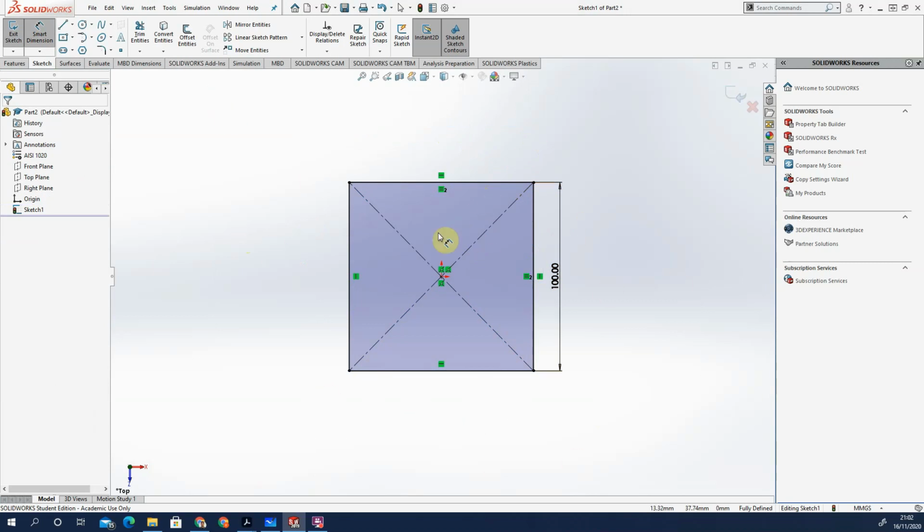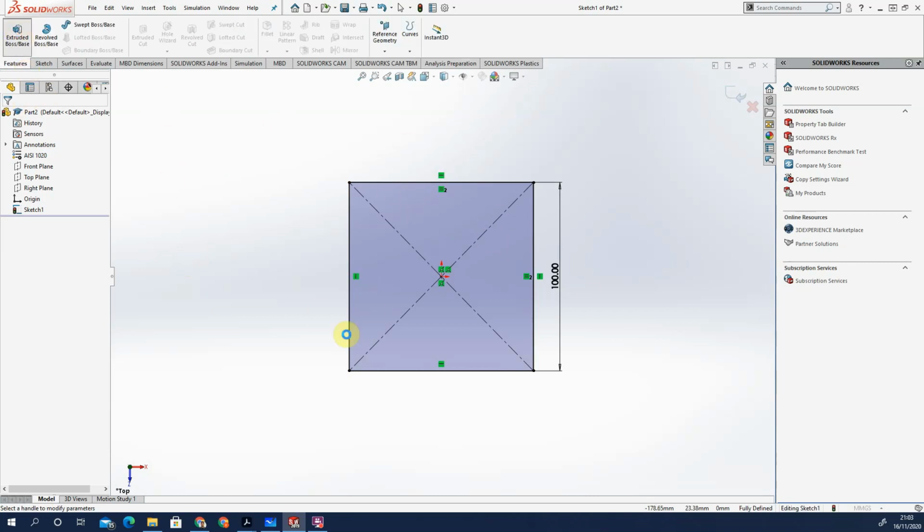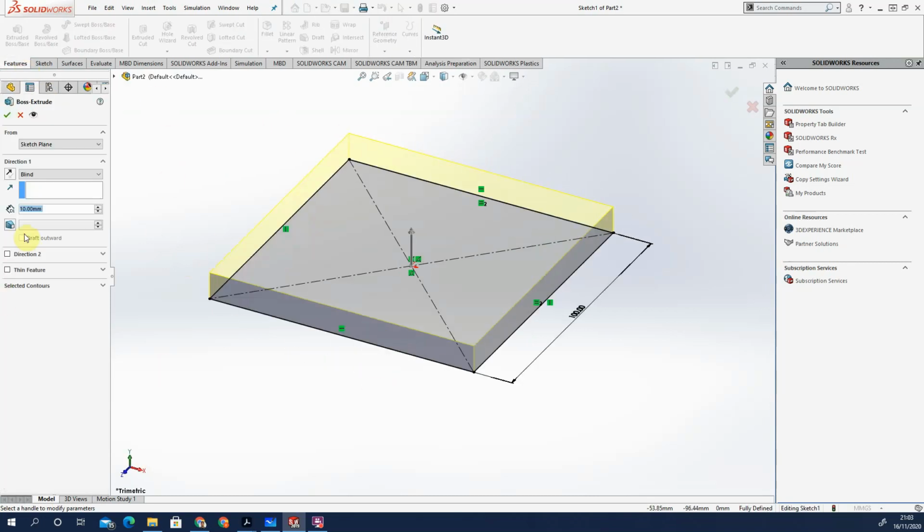So what I'm going to do is draw a block component that we're going to apply two chamfers to, a fillet, and put a hole through the centre. I'm going to show you how to do that. So I've done my basic square. Now I need to extrude the rest of my cube. So I'm going to get another 100 by 100 mil cube,